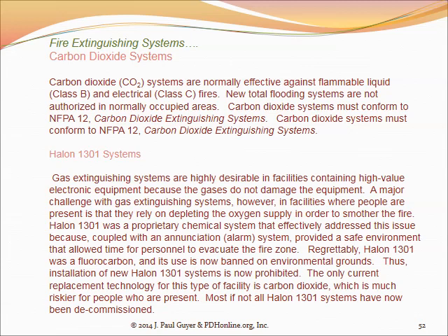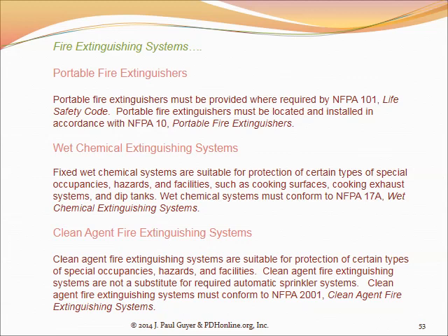However, before too long, they were found to be an environmental no-no. They're a fluorocarbon or something like that, and those were determined to be harmful to the atmosphere. So the original Halon 1301 systems have by and large all been taken out of service, but they have been replaced by different gas systems that do the same thing. They're typically called generically clean agent fire extinguishing systems, and they're used in areas like computer facilities and so on.